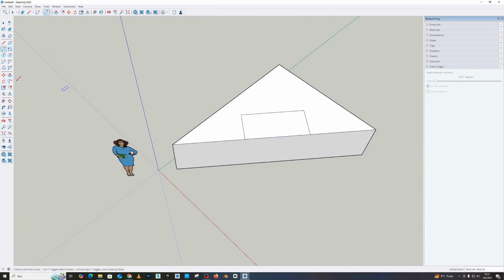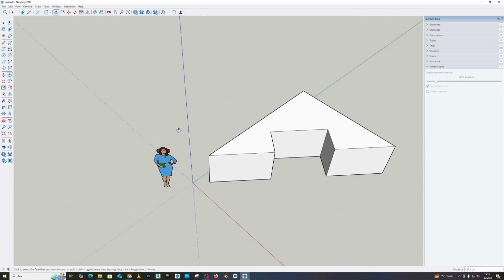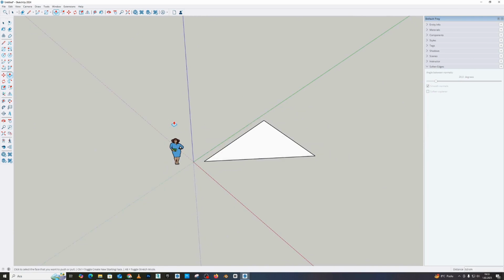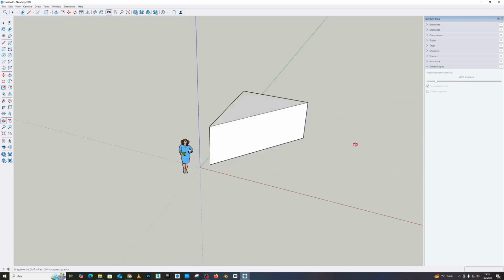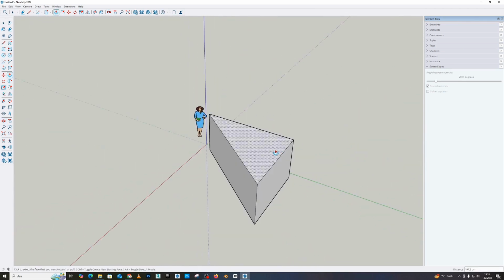Normally, when you draw from a section you want in SketchUp, you can cut and trim it, friends. Look, I drew the triangle in an instant and cut it. The only thing you need to learn here, friends, is that for a surface to form, 3 points need to meet. If 3 points meet, it means I can now lift it as a surface. What does it mean to lift it as a surface? I'm giving this a volume, a height, and now I'm adding a dimension to it, friends. Because 3 points create a surface for me.